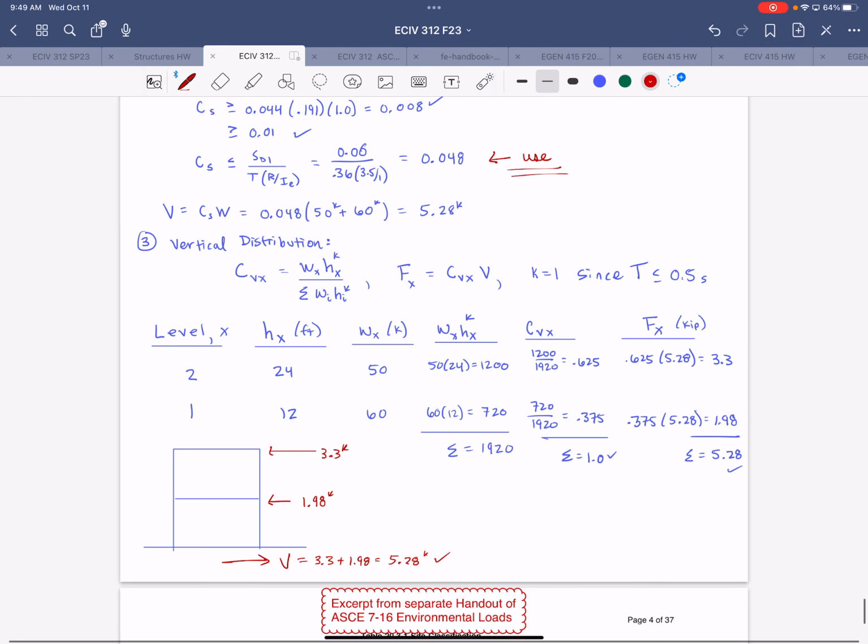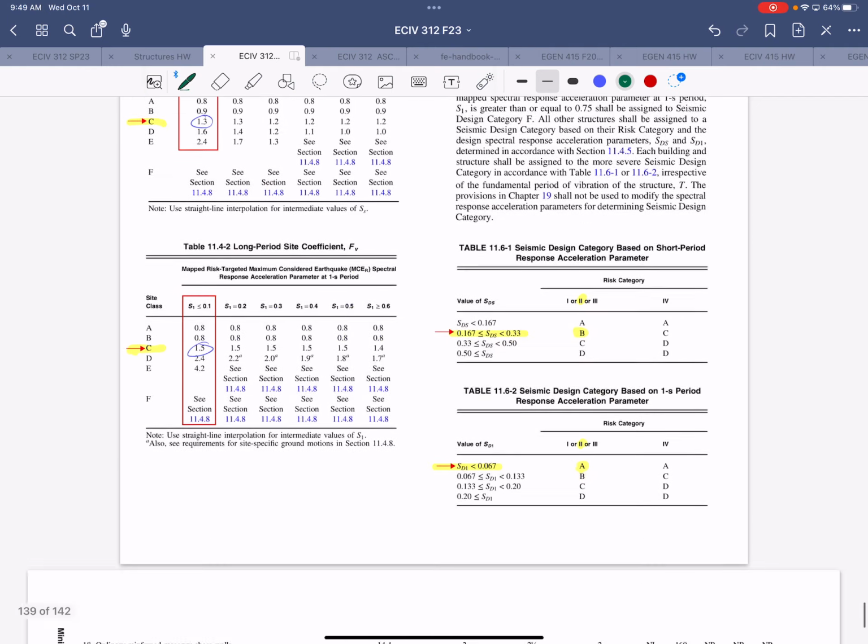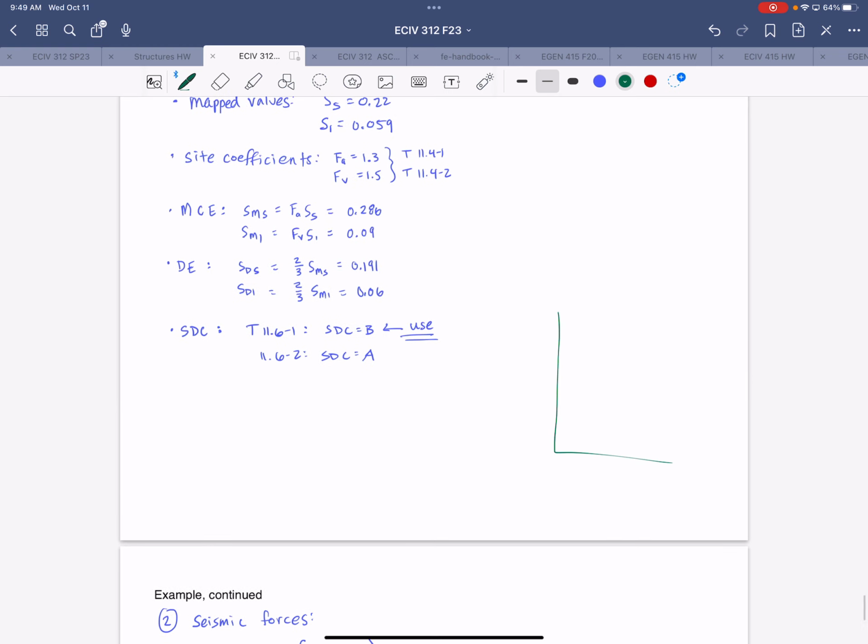They tend to fall in the longer period section of the response spectra. So let me just sketch it here, the response spectra like that. Taller buildings tend to fall over here with the longer period. And so the reason that they tend to perform better is because the magnitude of the earthquake that we need to design them for is a lot smaller. A shorter building in the same region would fall here, where the magnitude of the earthquake that we design for is a lot larger. So there's a couple different things going on with that comparison, but that's a good observation.